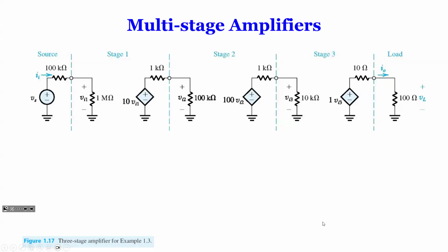Also, in the next class, you will be learning multi-stage amplifiers, because sometimes one stage is not big enough. One stage, let's say, amplifies by 10, which is not good enough, and we want more. Like in an op amp, for example, which we're going to talk about next chapter, we want to reach 5,000, 10,000. How can you reach that? Well, one stage is not enough. So you need multi-stage, like 100 times 100. If you have two stages, you get 10,000, right? That's good. So that's one reason you need multi-stage.